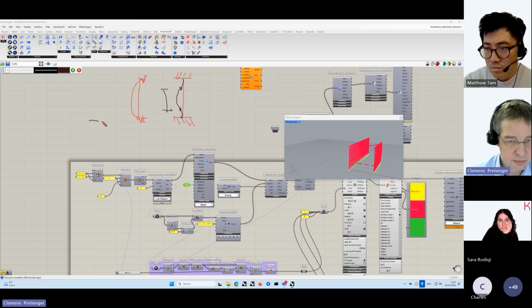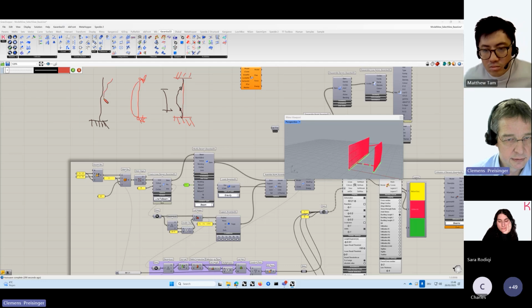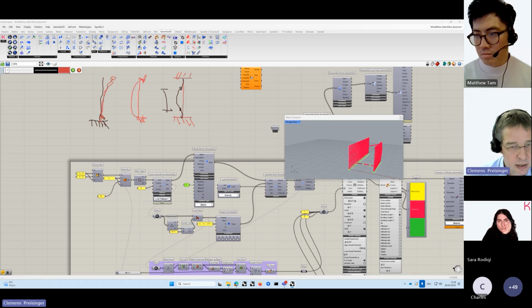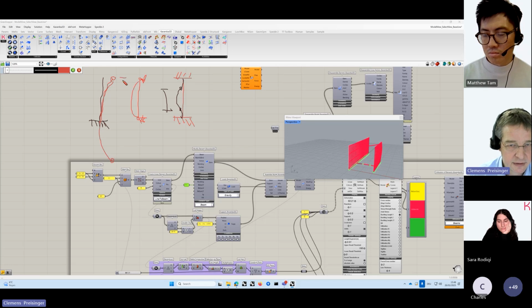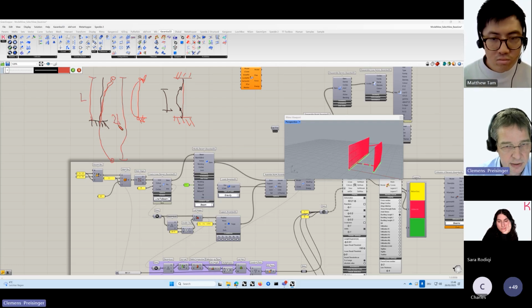Another case would be a freestanding column like this, which is cantilevering here. The buckling pattern would be like this here. There's one curve up here, with a zero moment, and maximum moment here, and it can be seen as a column which extends into the ground, and the buckling length in this case would be 2 times L. So these are the Euler cases.